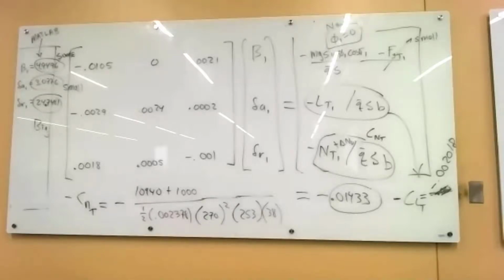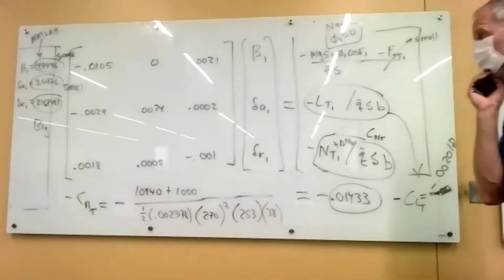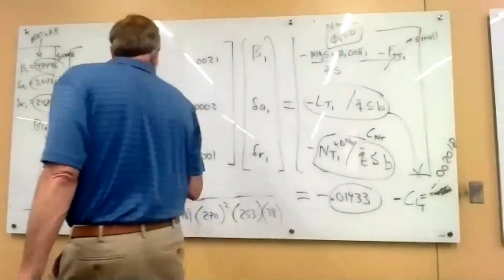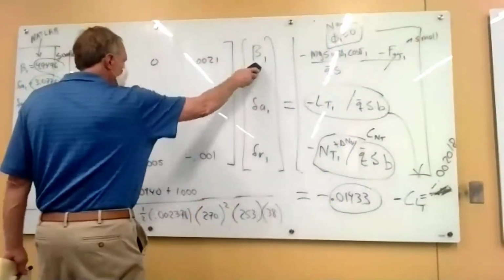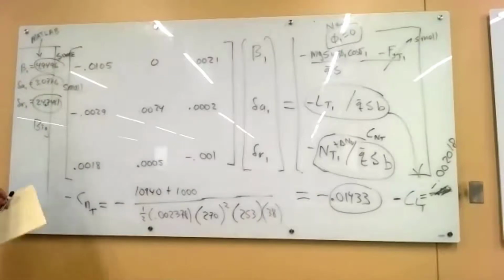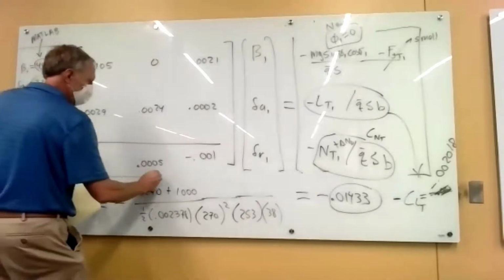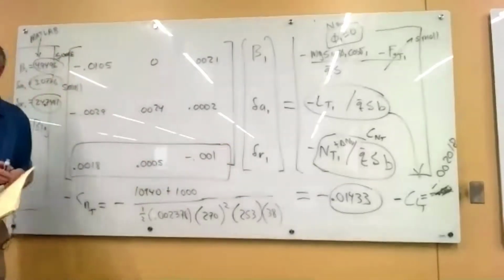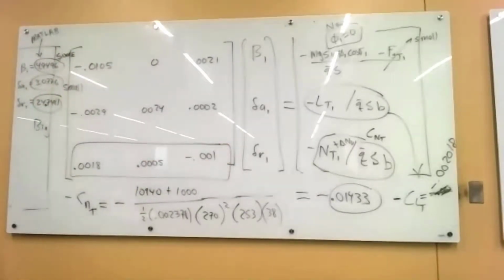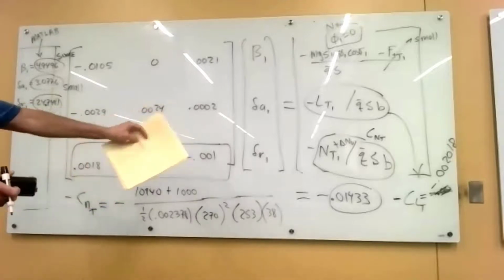Since the major effect that we've got going on is that we need rudder to counteract the yawing moment, and we saw that we didn't get a whole lot of aileron and a whole lot of beta, although we do get some, the biggest player in this is this bottom equation, because that's the yawing moment equation. So that's the one we can use to solve for rudder.